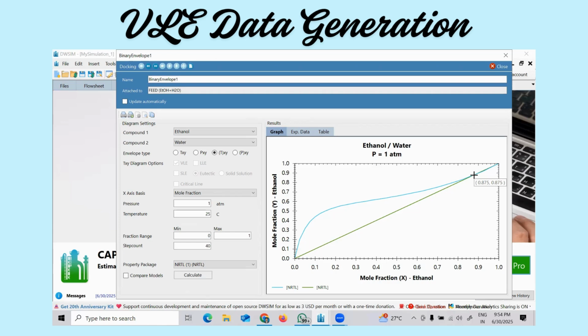Okay, we will see in another video how to generate other data, and then we'll compare in one simulation with other models also. Okay, hope you have understood how I've generated it, step by step. I request you all to make an attempt to generate such a diagram with the conditions given, and you can change the pressure and temperature also, and you can observe how the vapor liquid equilibrium curve is changing and how the azeotropic composition is also changing, right?